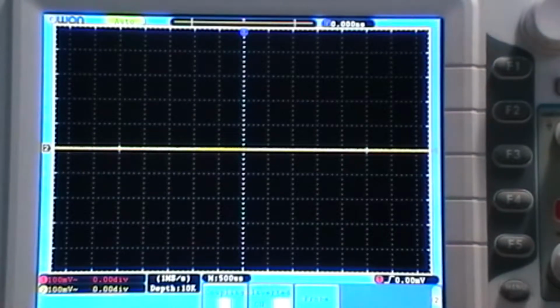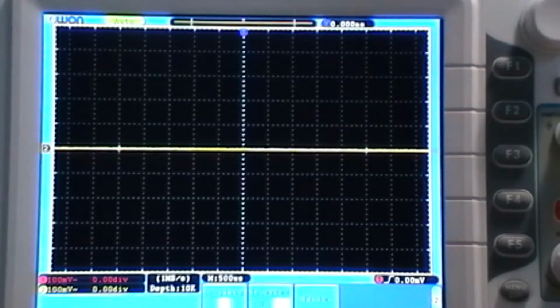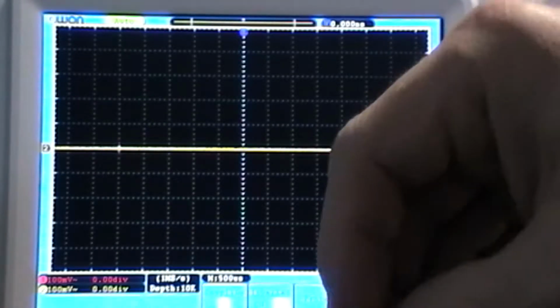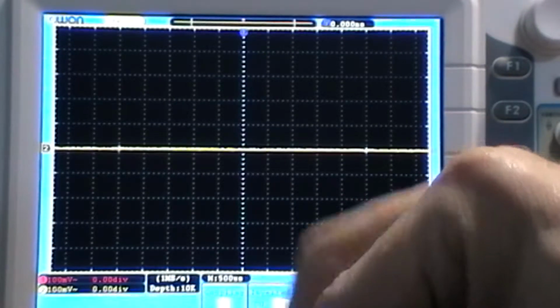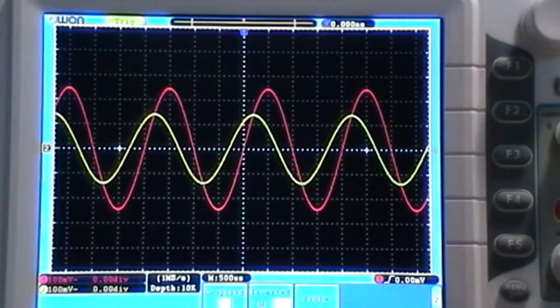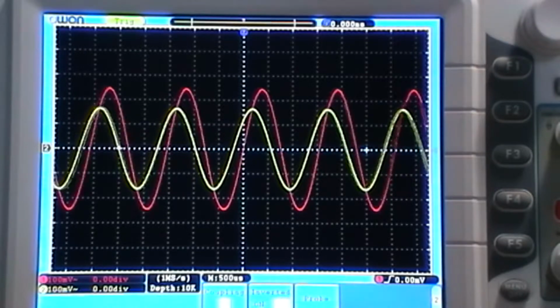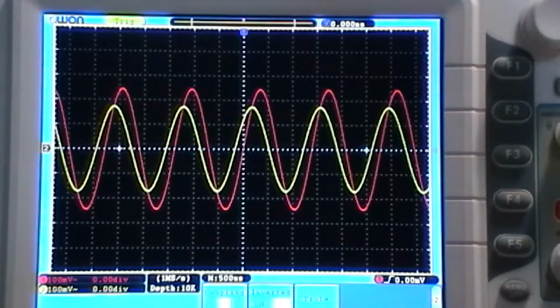Now, as I said, I'm going to use a 220 nanofarad capacitor. I'm not going to try showing it because it'll never focus at this range. Right, 220 nanofarad. So let's turn the scope on, and we've got some attenuation. Now, according to my calculations, the cutoff frequency for the 220 nanofarad is 723 Hertz.